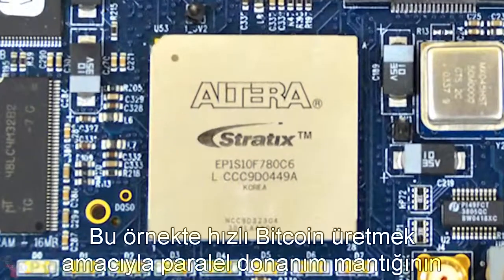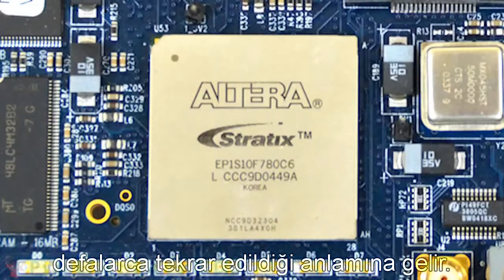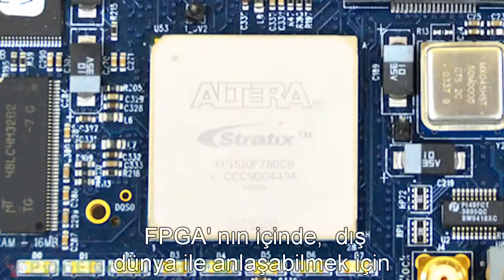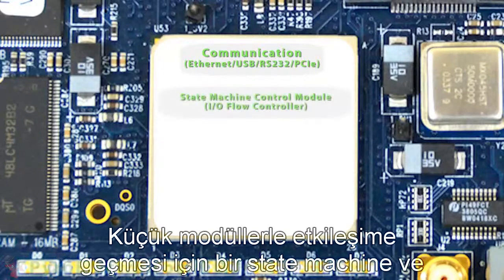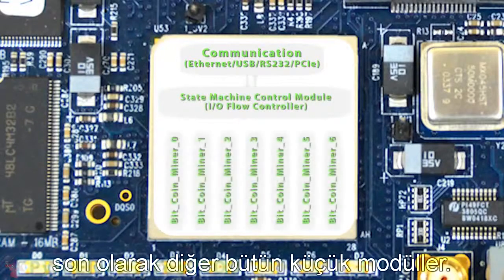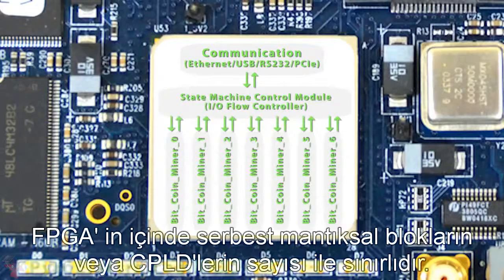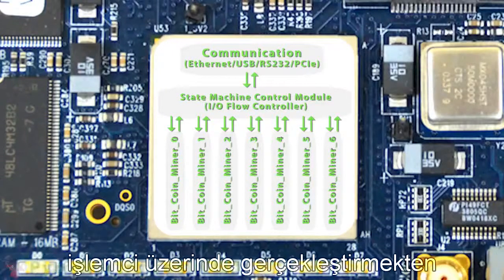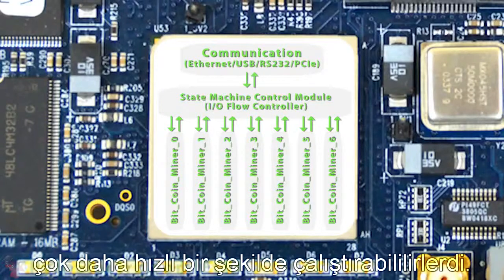As an example, pretend we wanted to harness the power of parallel hardware logic to build a fast Bitcoin miner, which means performing an encryption process over and over. Inside of the FPGA, we would need a communications module to talk to the outside world, a state machine to interact with our miner modules, and then finally, all of our miner modules. The number of parallel miners or encryption modules would only be limited by the amount of free logic blocks in the FPGA or CPLD, and they would all be able to operate in parallel, making it much faster than performing the same operations on a processor that must run instructions one at a time.